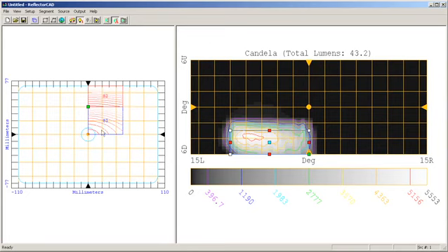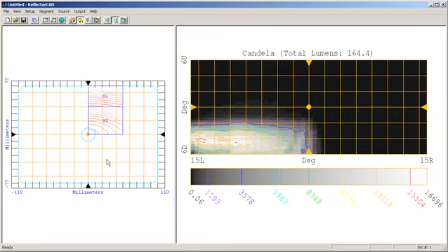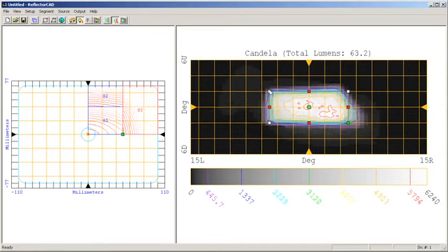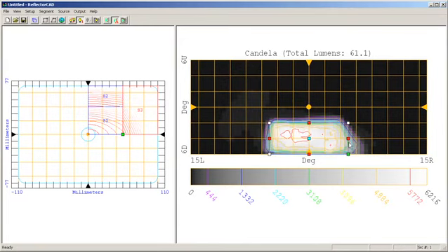Now, I can click outside of the segments which I have defined, and I see the sum total of the luminous intensity patterns from each of the individual segments. Or I can actually click on each individual segment itself and see the contribution from that. I have two segments defined. Now I'm ready to create a third segment. This is a luminous intensity pattern from the third segment. I'm ready to reposition this third segment to give the desired performance that I want from this segment.